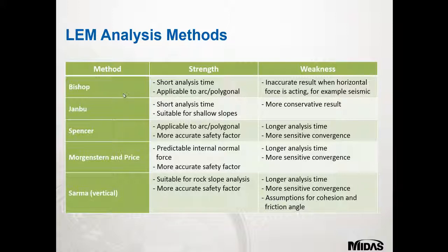For more complex problems involving highly heterogeneous ground with layers of different materials between adjacent layers, and where the interslice shear force is expected to vary, one can use the Morgenstern-Price method using variable functions for modelling interslice shear forces.